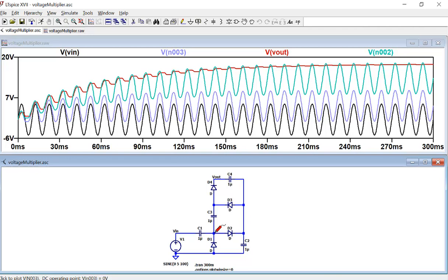So that's why it lifts the lowest DC voltage at this point from -5 to 0. And the same concept for here. It lifts the lowest DC voltage from 5 to 10. So now the lowest DC here will be 10, and everything will be built up upon that DC voltage. And then it's being rectified, so you get V out.